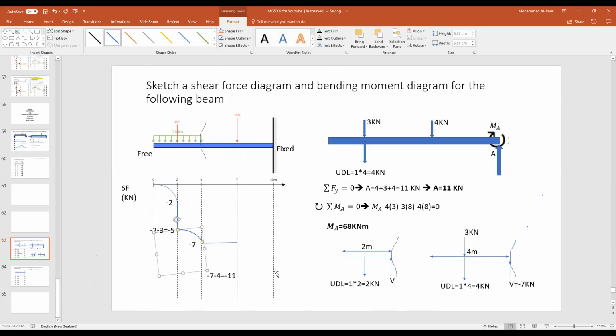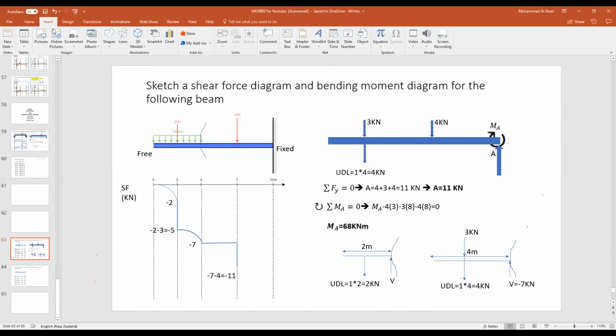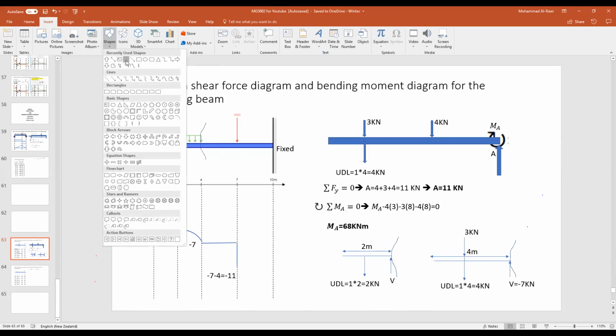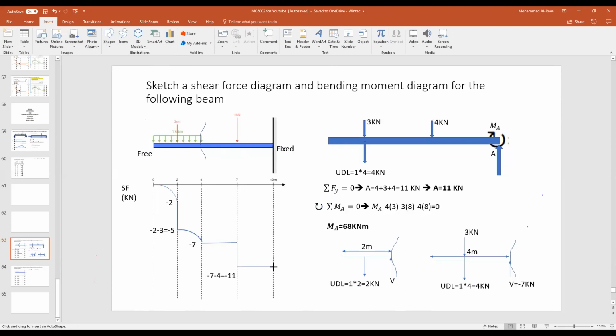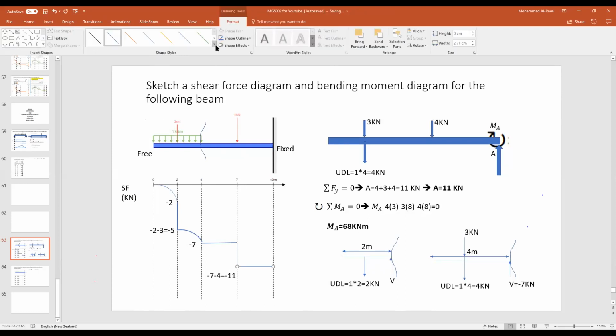By the way, those curves should be improved. They should be smoother and nicer. Now, one thing, again, I've made a mistake and no one is correcting me, which I need to fix now. I'll tell you very soon. I confused myself. So again, no load going in that direction. And then that's -7. The support reaction is equal to -11, and that is equal to 11. And then I go in that direction to close the diagram.